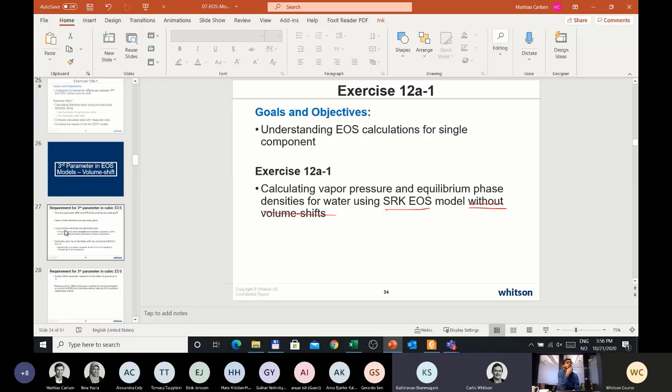Yeah. And the question, could you just repeat it one more time? It was a little bit low. What I was asking is, for example, in a topsides process simulation using HYSYS, whether it is SRK or Peng-Robinson, we have found that both of these struggle when there is a transition to dense phase. So in that case, HYSYS has an option while defining the fluid package to force it either to the liquid phase or to the gas phase by a dense phase tuning factor.